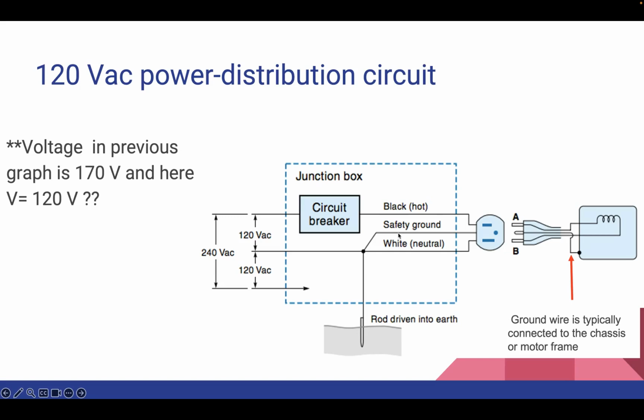It's important to understand the concept of voltage in an AC circuit. The designation of 120 volt AC indicates the effective voltage, as if the power content were constant over the entire cycle. The highest instantaneous voltage on prong A, referred to as V peak, can reach up to 170 volts. This discrepancy arises because the effective voltage accounts for the varying power content through the cycle.